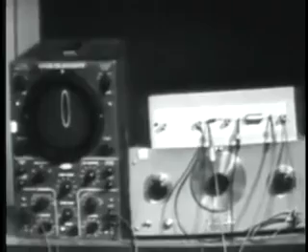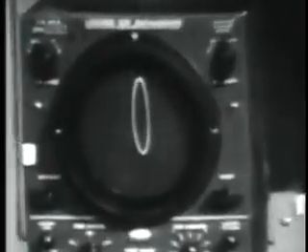Now, we have the first one on here, and the first Lissajous pattern is simply an oval which indicates two voltages exactly 90 degrees out of phase. But you may say, I thought two voltages 90 degrees out of phase were supposed to give me a circle like this. Well, true, it would be a perfect circle if the two voltages were out of phase by exactly 90 degrees and equal in amplitude. However, the two voltages in our problem are not equal in amplitude.